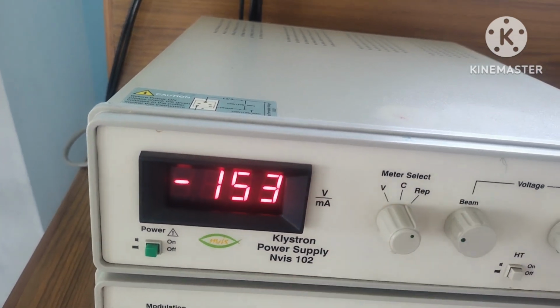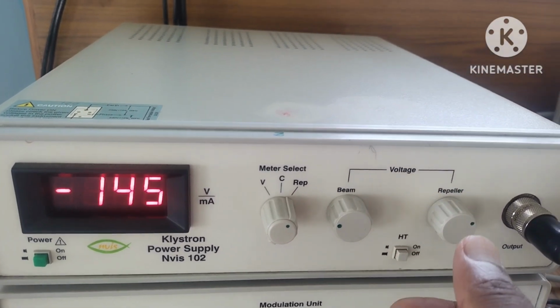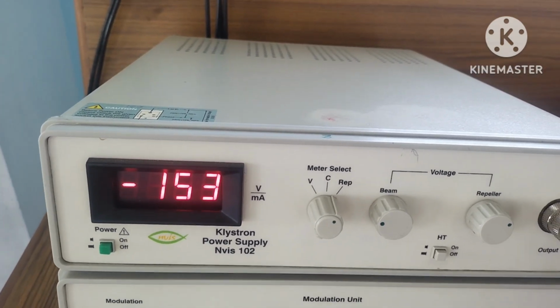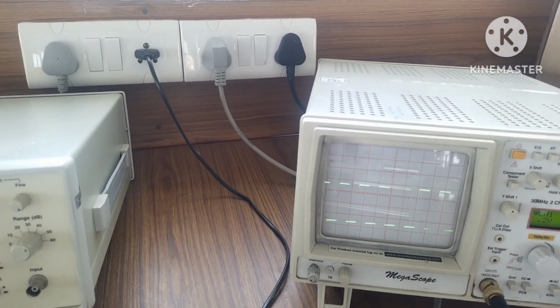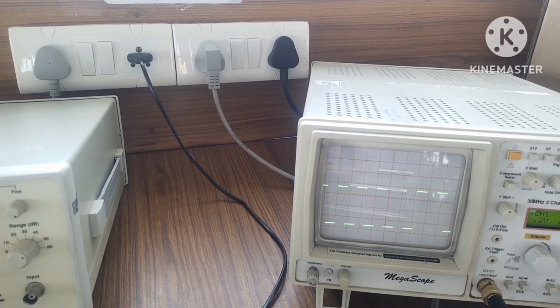By adjusting the repeller, we have to observe a perfect square wave in the CRO. If there is a perfect square wave in the CRO, then we can say the bench is operating under the perfect condition.